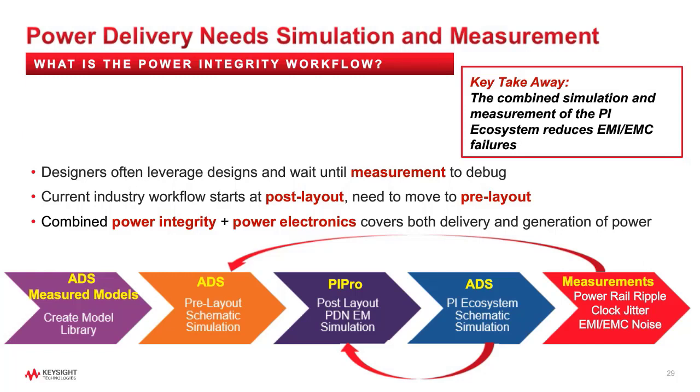A final post-layout PI ecosystem simulation then connects the high-fidelity VRM model with the PCB EM model, the optimized decoupling capacitors, and the package die model to look at both small signal AC impedance and load transients, as well as large signal DC to DC converter switching ripple. The final step in the power integrity workflow is measurement to verify that the ripple is within specification, that load timing and amplitude jitter is acceptable, and that EMI/EMC standards are met.